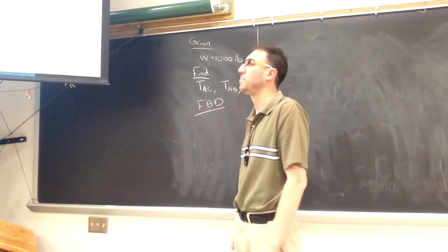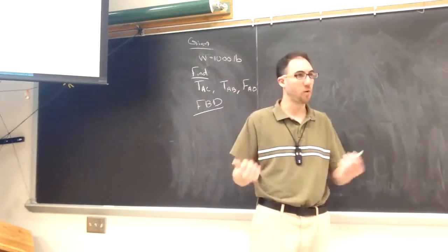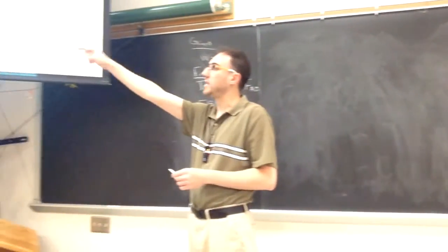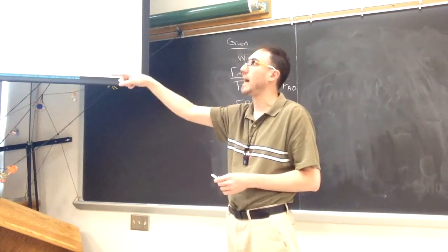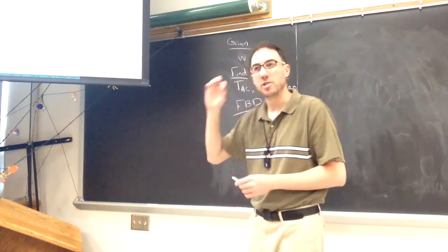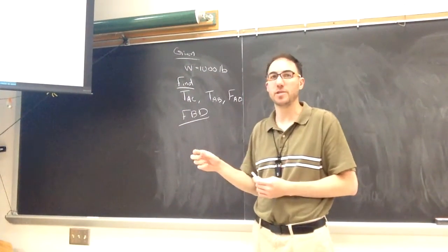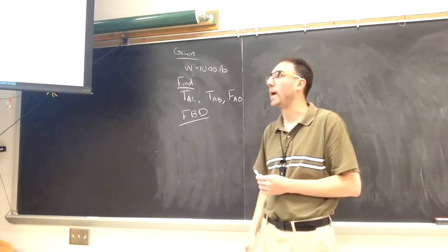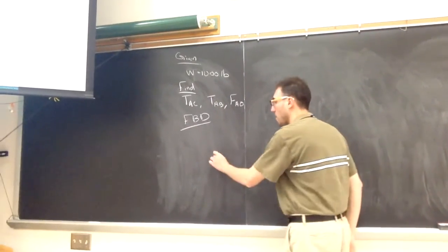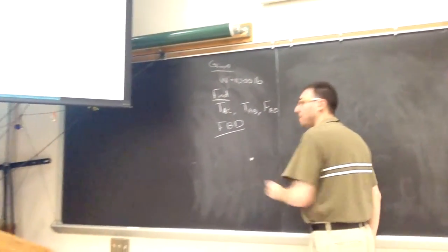In this case, which point are we going to model the forces acting on? If we look at A, the weight's hanging from it, and cable AC, AB and AO are attached to it. So if we choose point A as our point of interest, all 3 forces we're interested in act on A, and the weight will also act on A. That is our point of interest here, point A.